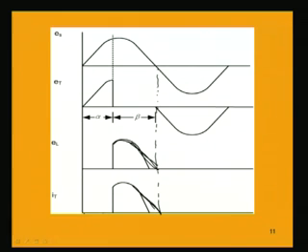Till the firing of the thyristor takes place, the current is 0, no conduction is taking place till alpha. After alpha, conduction starts, current starts flowing, and the voltage across the resistance is of this shape. So, the current also has this shape only, because it is a purely resistive load. So, in this figure we have seen that the voltage and current across the load are present only for this portion of the whole half cycle, and in the other half cycle it is totally 0.